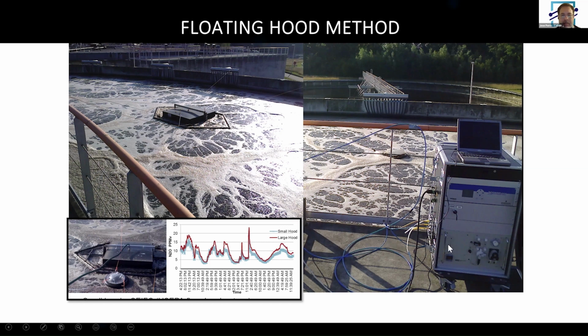Depending on the analyzer, not only might you be able to measure N2O, but also methane, CO2, and oxygen. But obviously we're interested in the N2O. So here we can get our N2O measurements. But as you can see, there's quite a bit of equipment involved. You also have gas cylinders you might have to transport for calibrating the analyzer.